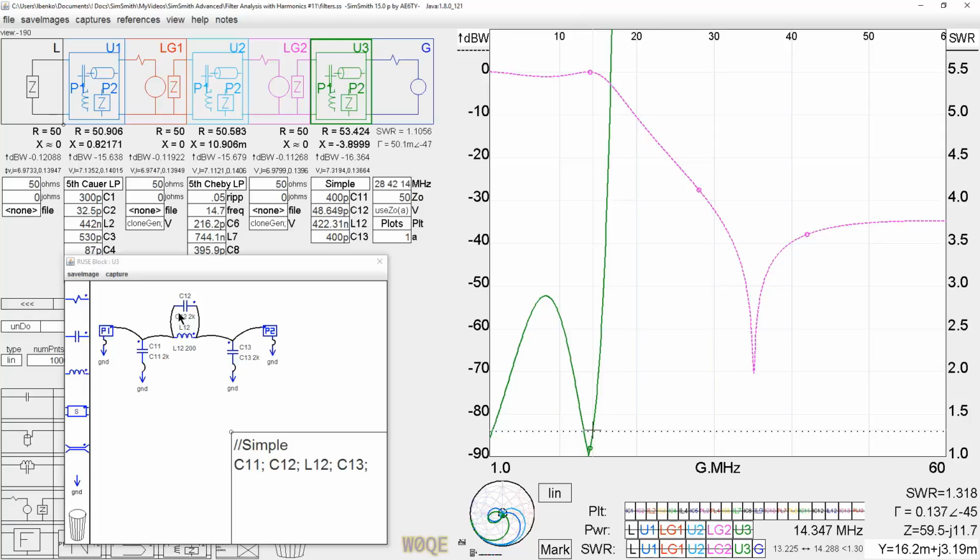This circuit with this big capacitor here, when I say big, it's fairly significant, means we cannot use this as a low-pass filter at anything other than the 20-meter band. The loss we see up here is due to mismatch loss due to this SWR. Our second harmonic is 27.5 dB down, which is not 43 dB. Our third harmonic is 38 dB down.